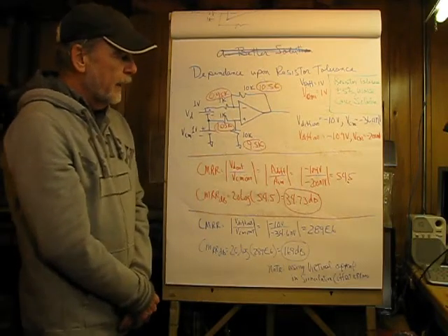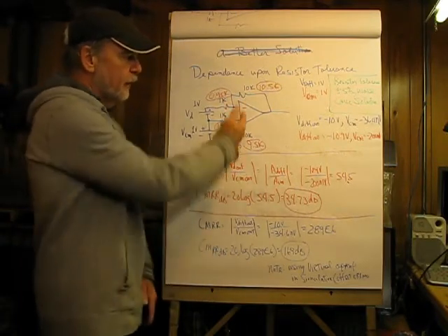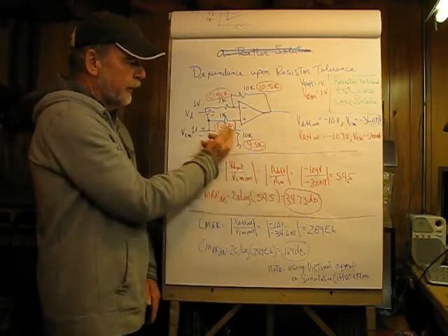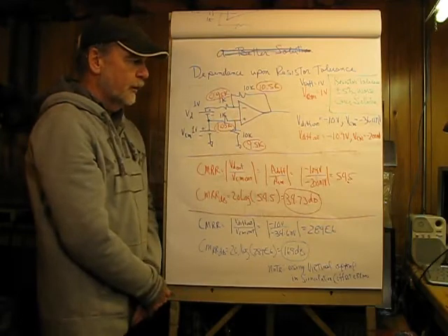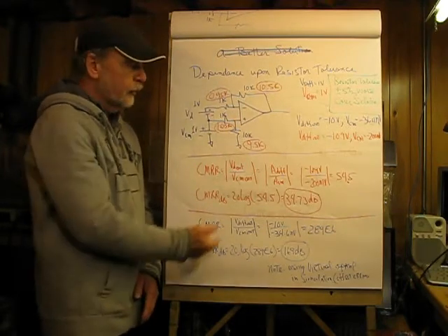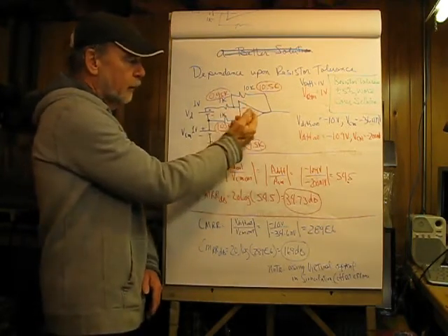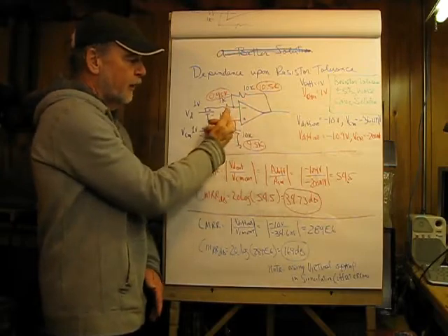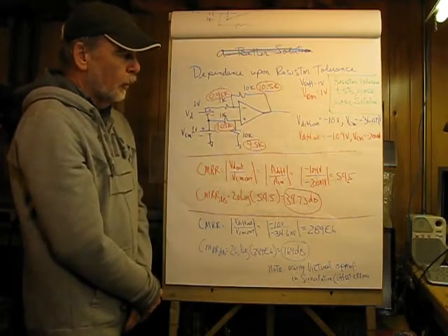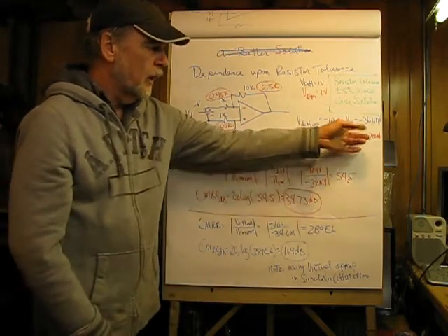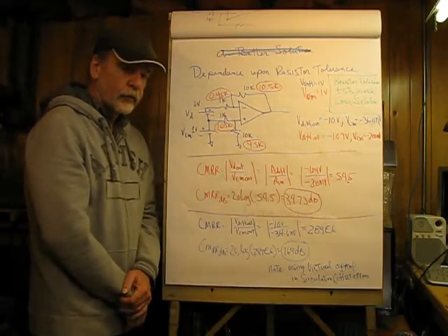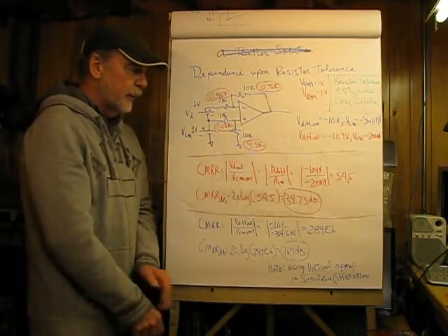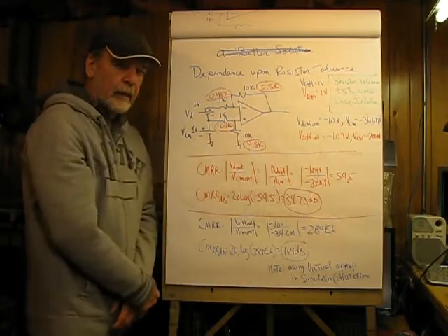So what we have here is, if everything is proper, 10 volts and 1K, our output is going to be negative 10 volts, as we would expect, because the gain of this circuit would be negative 10K divided by 1K. And what we see for the common mode voltage in the output is negative 36.4 nanovolts, and realistically that may be due to features inside the op amp.